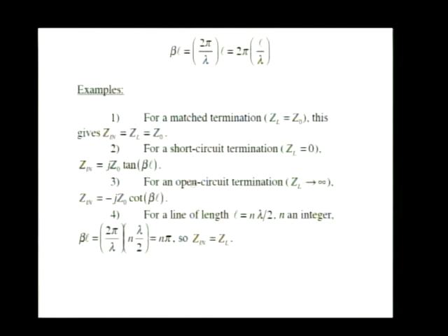at RF. Just because you maybe hook a section of wire up to the output terminals and short circuit at the end of that wire, you haven't short circuited the terminals. The terminals will see that input impedance of a section of transmission line. So unless you actually weld those terminals right there at the device together, you're not going to have a short circuit at those terminals. You put any piece of wire of any length whatsoever, no longer a short circuit or an open circuit. All right.